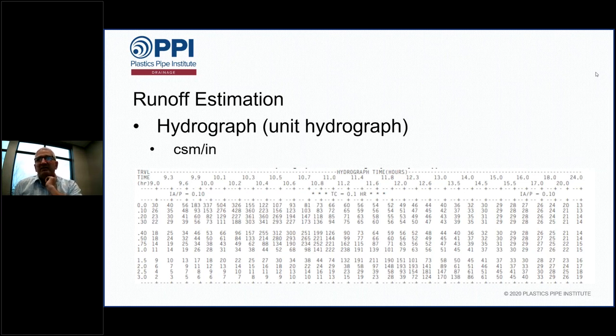What that's telling me is I take that 183 and I multiply it, because it's per square mile per inch of runoff. So I have to convert that number based on the values that I got in my unit discharge and my drainage area. And so that's how I convert these numbers. And from that, I can go along the x-axis, picking values, and I can build a hydrograph using that particular method.